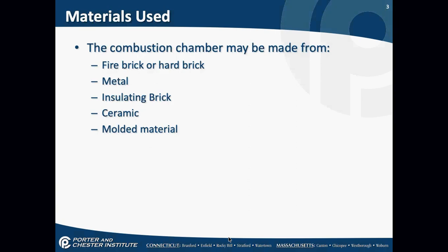Okay. Combustion chambers can be made of fire brick, metal, insulating brick, ceramic, or a molded material. We are not seeing in residential anymore a ton of brick combustion chambers. We are seeing molded material, synthetic molded material, as our primary combustion chamber now. But you still have to know about these other things because they still exist in commercial or larger applications.